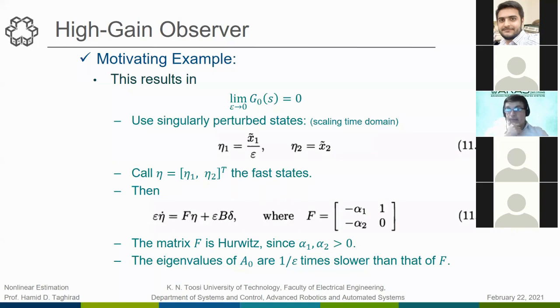So when we are using an observer, we should use a robust controller? Not necessarily. We should use a controller that stabilizes the system. So there are two separate problems. As I mentioned in the beginning, I don't know if you were in my morning session, in linear theory we have a separation theorem. We can design a controller separately and design an observer completely separately, in two different avenues, and then add them together.